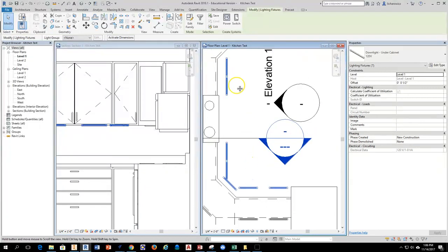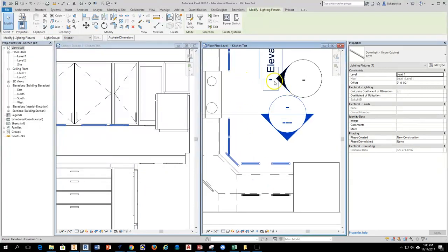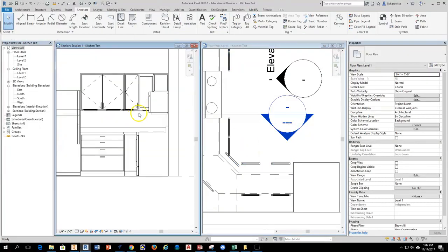So they're the lights that I want to go down to the toe kick. When I do this, I'm going to now come over here to the offset, and from the bottom of the standard cabinet height, I'm going to highlight, and I'm actually going to type in the distance down to the toe kick. Well, how would I just even know what that is?